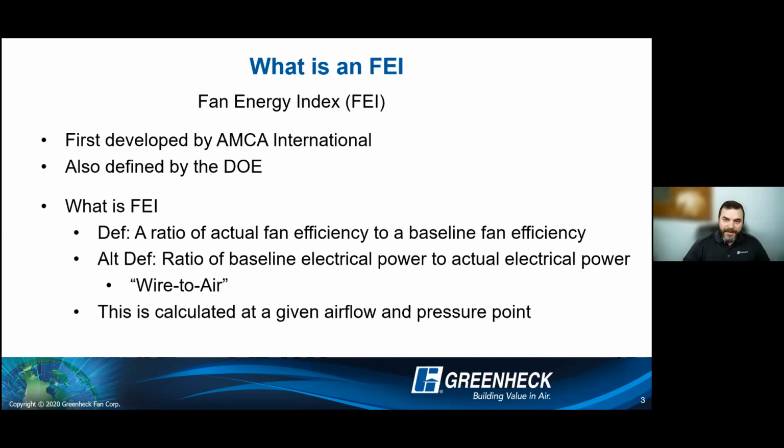So with all that said, this is an excellent single value way to compare fans in an application, taking into account variables such as fan size, your system's pressure, proper applications, if a VFD is being used, direct drive versus belt drive.